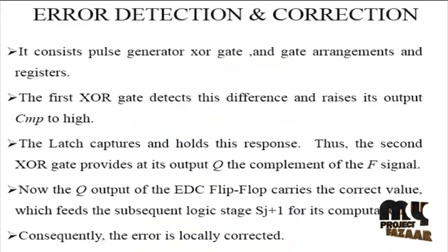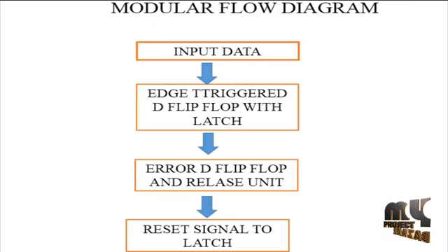After that, the process is fed into the latch. The T latch or transparent latch is a simple extension of the gated SR latch that removes the possibility of invalid input states. Since the gated SR latch allows us to latch the output without using the S or R inputs, we can remove one of the inputs by driving both the set and reset inputs with a complementary driver. We remove one input and automatically make it the inverse of the remaining input.